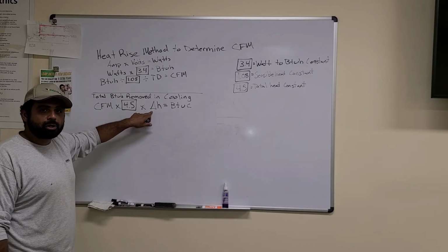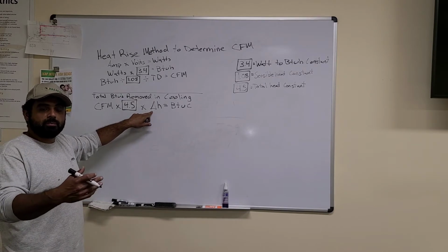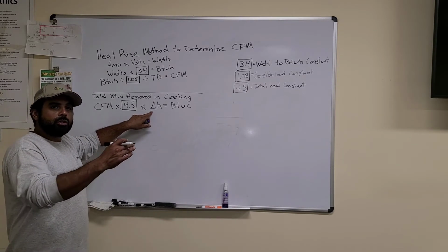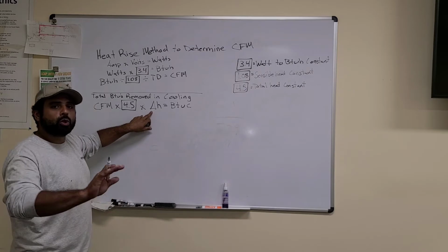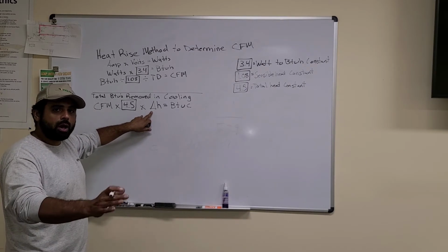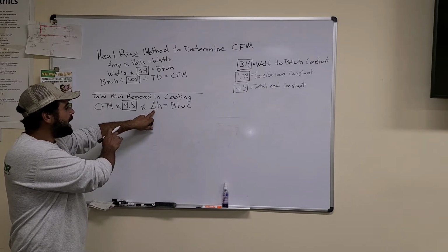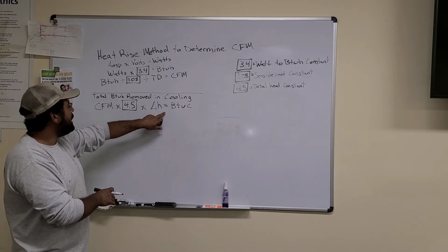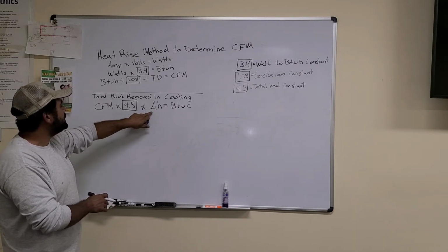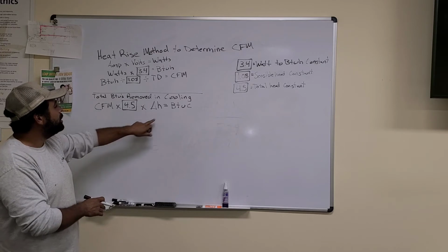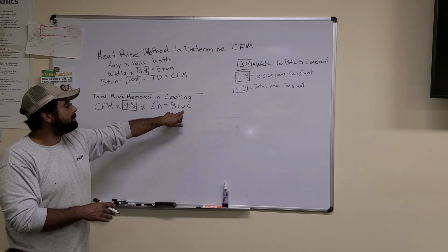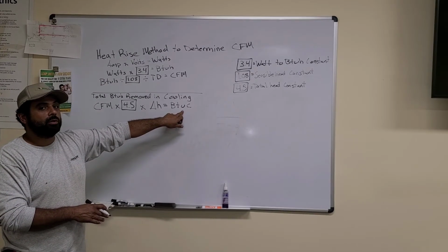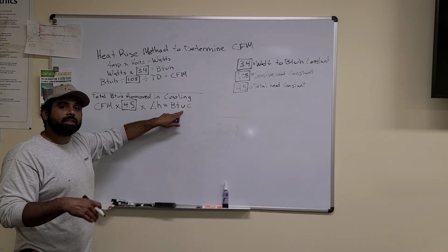You'll be able to easily determine total heat in the return air, total heat in the supply air. Compare those two numbers. It's going to give you a change in delta H, or a change in enthalpy. And when you plug in the rest of these numbers, your CFM that you solve for, your change in enthalpy that you solve for, you'll be able to solve for BTUs in cooling. We're going to go back over to diagnostic and do that.